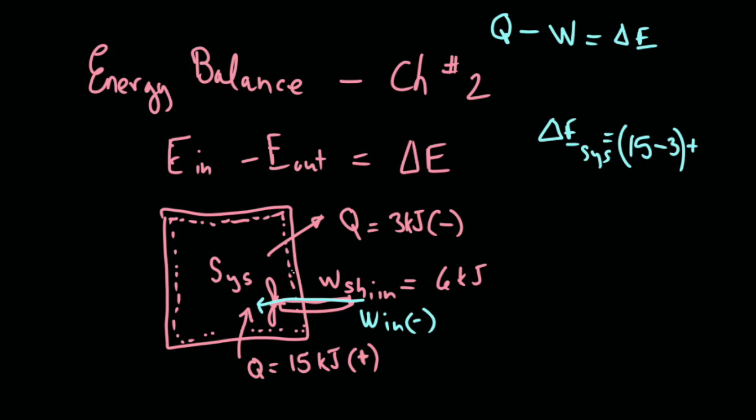Positive work would be work coming out of the system. For example, an engine that produces shaft work, we consider that positive work. So that would be coming out of the system. But again, don't confuse the sign convention. So therefore, because work is negative, but yet we have this other negative sign here, this actually becomes a positive here.